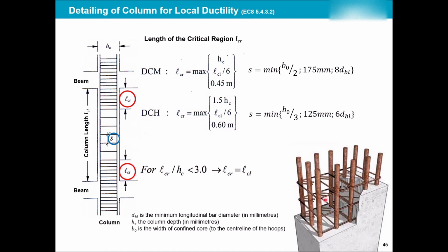As you can see, the hoops are around it. This has lots of longitudinal reinforcement, so the hoops are a little more sophisticated, let's say three of them. And if you remember, the closure of that reinforcement should be at 135 degrees, not 90 degrees, which we used to do in non-seismic areas.